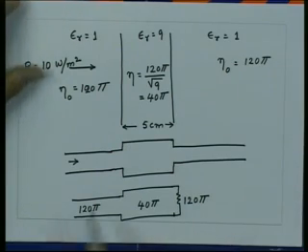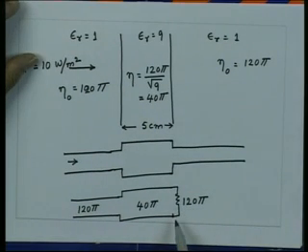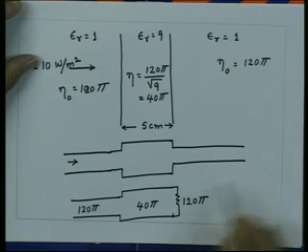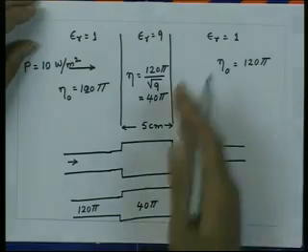If you go by the transmission line approach, essentially what we can do is find out what is the impedance which would be seen at this location, then how much power has been transferred to that impedance. That is the power which finally will be delivered to this impedance. So, we can get the power, and from there we can find out the power which is transmitted to this medium.